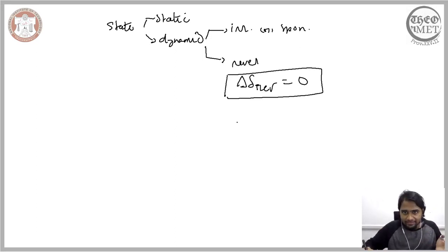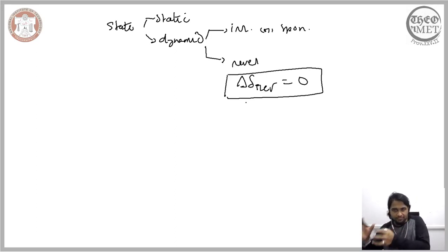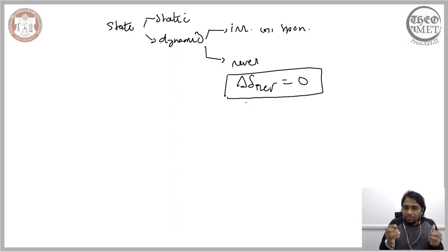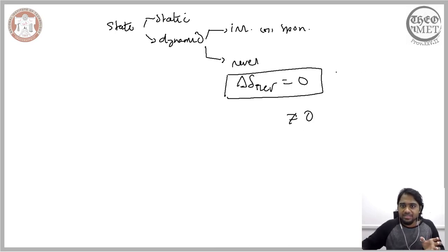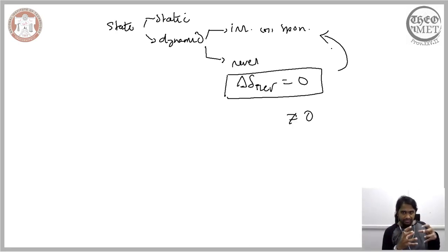So this criterion, which we arrived at largely based on the second law of thermodynamics, helps us describe if the dynamic system we are considering is experiencing a reversible change or an irreversible change. When the summation of the change in the entropy experienced by a dynamic system is not equal to 0, then the system is experiencing an irreversible change. So the criterion states that the overall change in the entropy when the system is experiencing a reversible process is equal to 0.